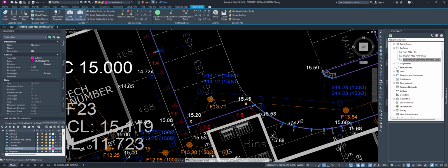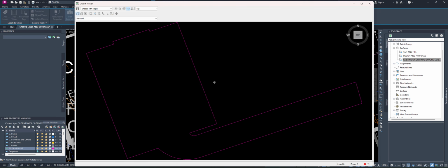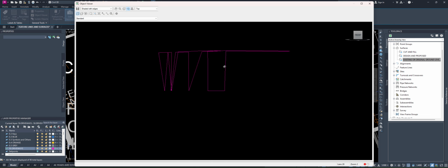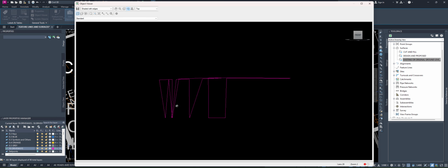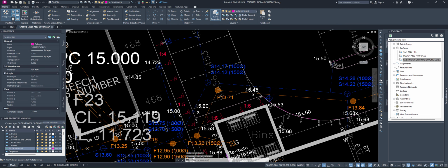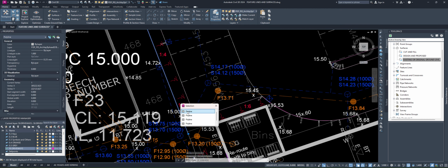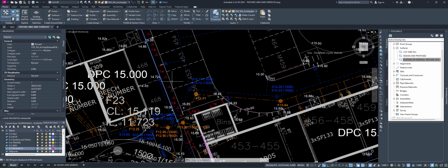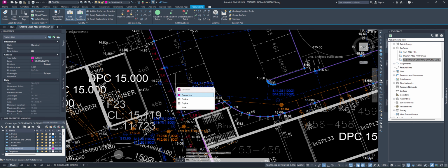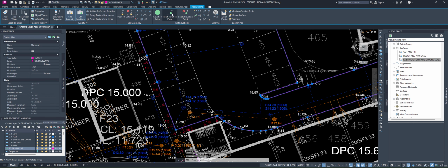Okay, let's again give a quick look on our line work or our 3D lines under front perspective of the camera. We can see we got quite a lot of spikes. That's gonna be very easy to be fixed. Again, we need to chase all the zero elevation, all the vertices with the zero elevation.